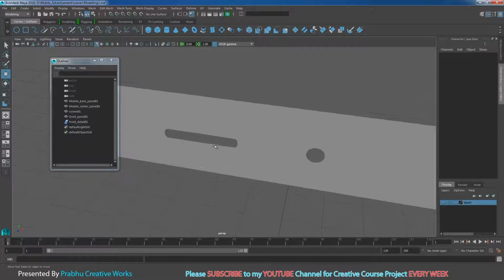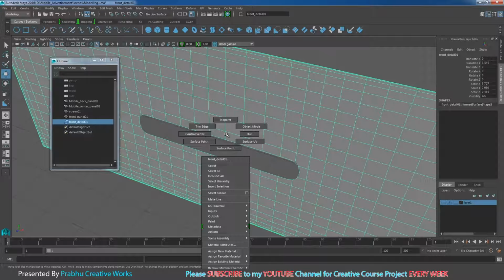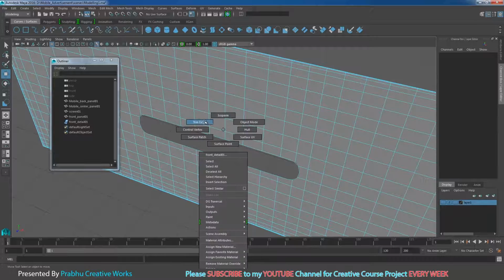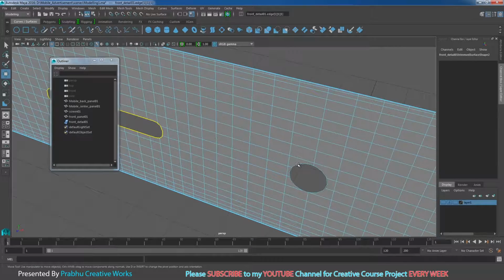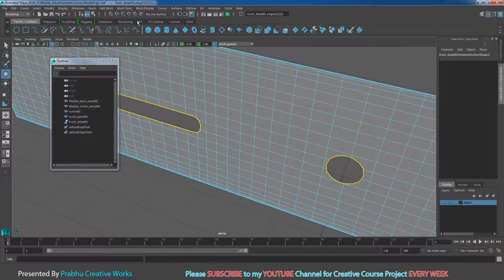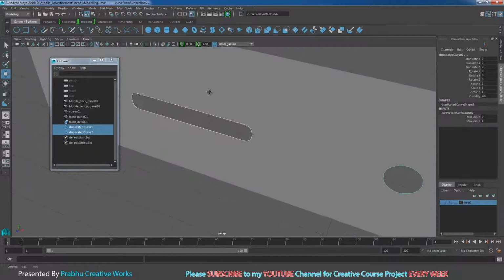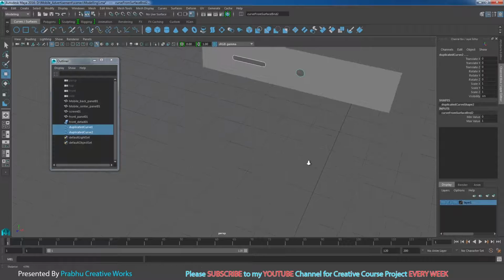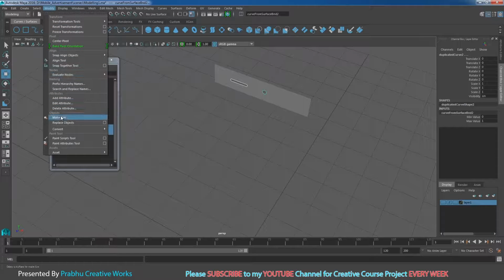So now we want some thickness for this area, so right click and choose trim edge and select this trim edge and shift select this trim edge. Now go to curves and choose duplicate surface curve. So that means you got two curves over here. So our pivot will be in the center of the grid. So with the two curves selected, go to modify and choose center pivot.